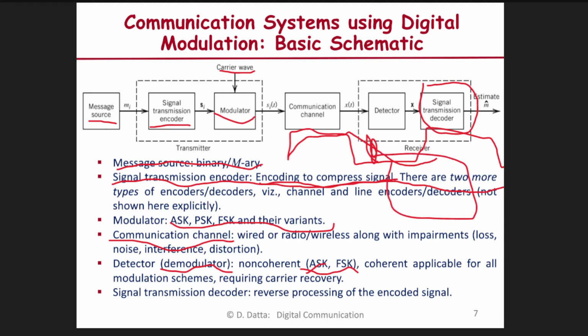Okay, and that will receive the signal from here. It will be tapped from here, and then it will go there. So the clock recovery, carrier recovery, frame synchronization, all will be done through this, and the recovered clock and recovered carrier will support the whole receiver as a subsystem.